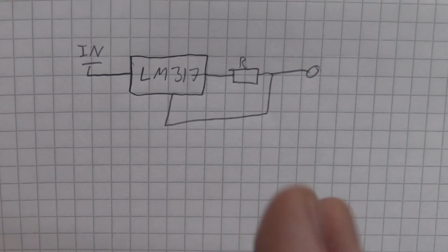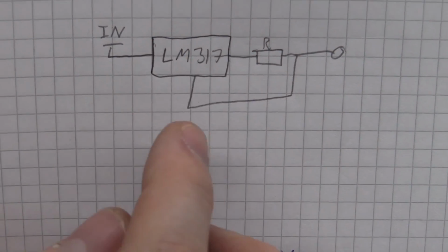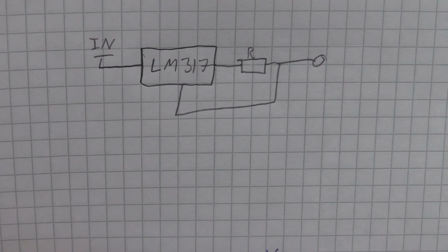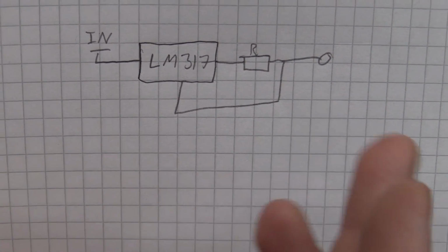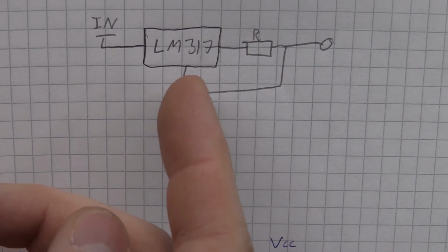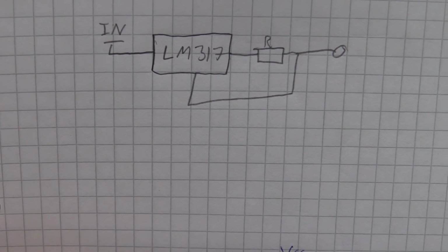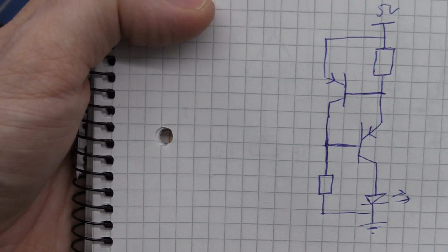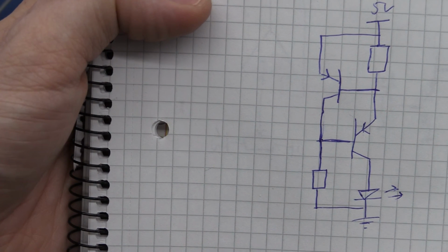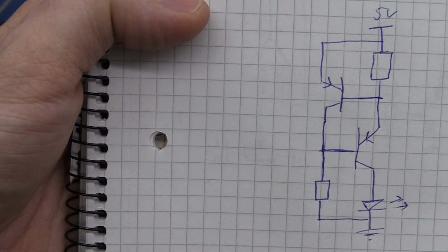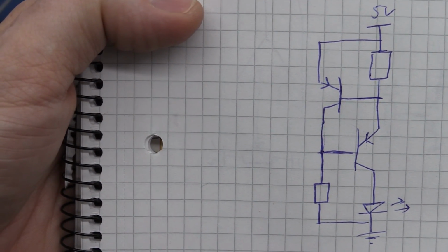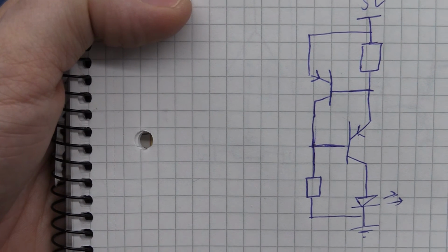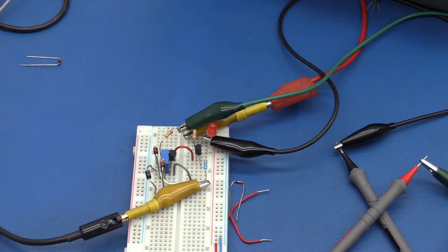Of course, the option to go with if you are manufacturing a product in higher volumes is of course just to buy an IC that does the job. They are pretty cheap, maybe even cheaper than the regulator here. Just again, if you want a fixed current, maybe a circuit like this would be cheaper than the IC, but again then you would have to design and test it. Consider if your time is worth more than the cost of the IC. That's always the trade-off. So now we covered some of the linear current regulators.